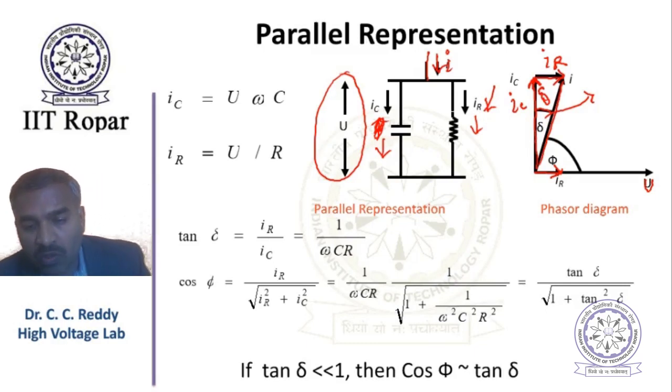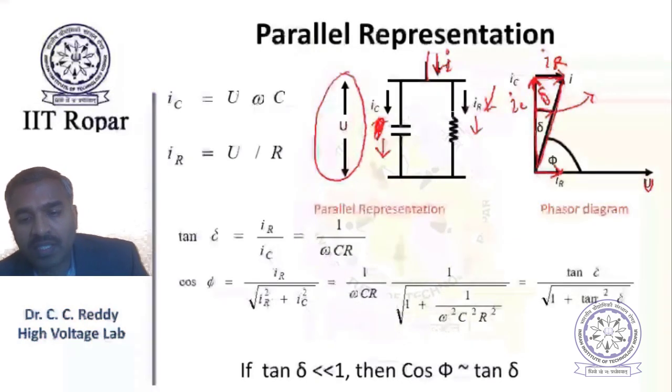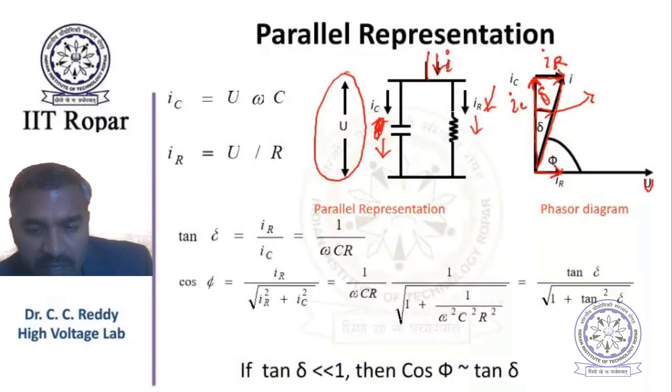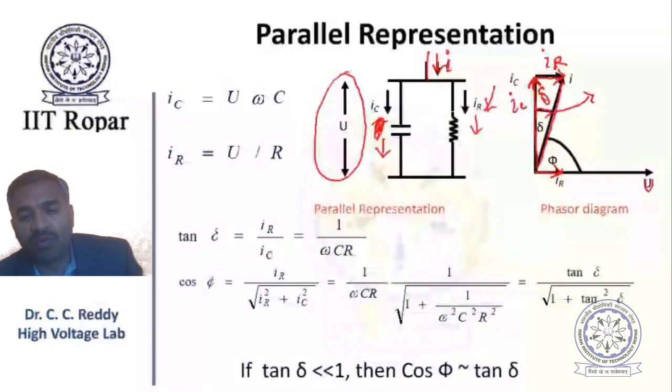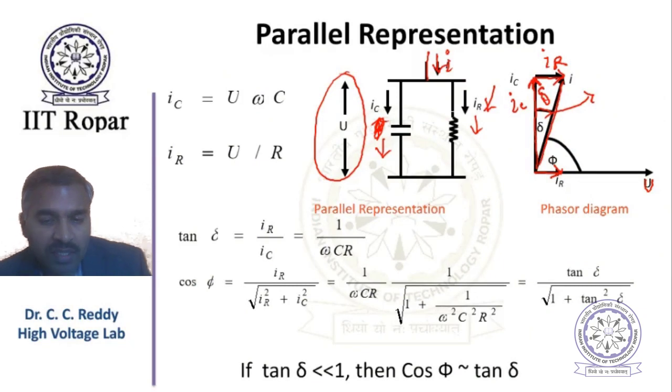The capacitive portion is the useful current; it represents how pure the dielectric is, how pure the capacitance is. IR indicates the lossy portion, how much loss it has. The ratio between IR and IC represents the relative loss, meaning for this much capacitance, this much loss. That is what we are interested in, to tell the status or to diagnose the insulation condition.